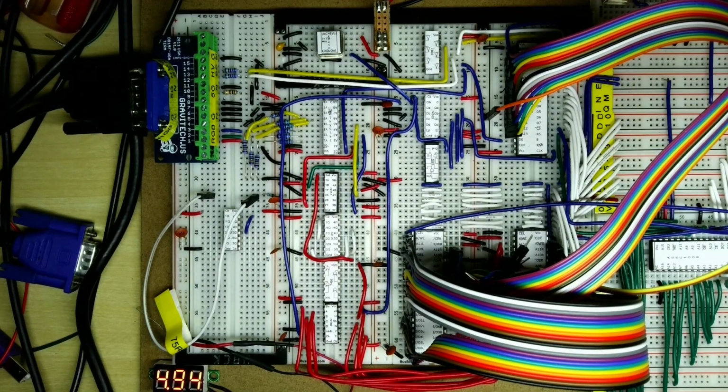I've also added a couple of decoupling capacitors, so where I hadn't got decoupling capacitors, I have added those. Okay, so in the next step, we're going to add the cursor support, and then after that, we will try and change the timing signals so that we get the display completely centered in the video capture card and also the monitor.